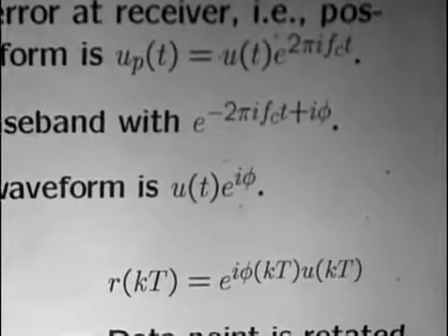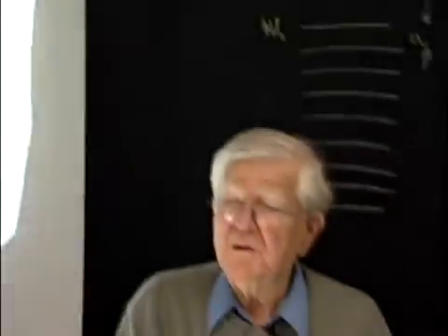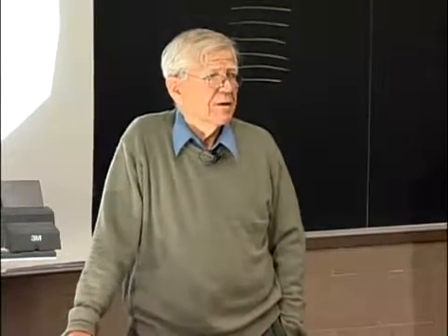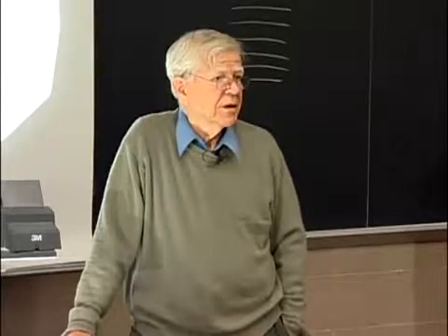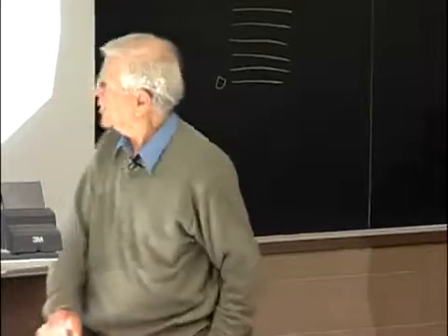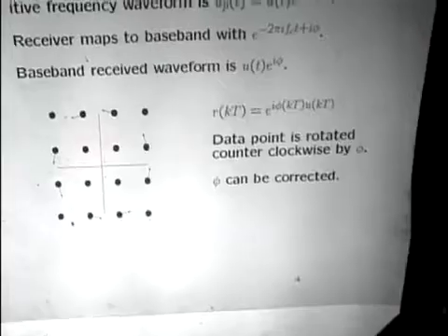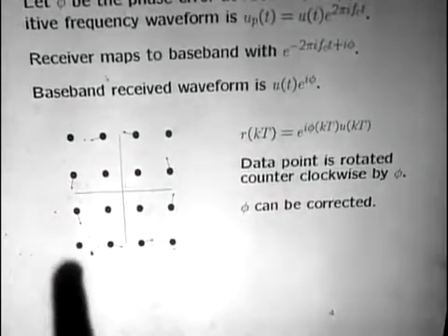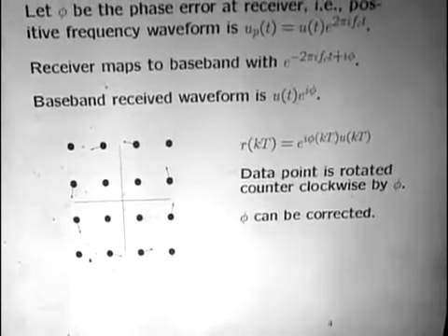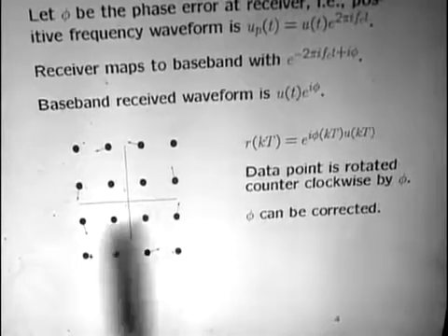Now suppose you're sending analog data. What happens here? Well, with analog data, you're absolutely up a creek without an oar. Okay, there's nothing you can do. But with digital data, there is something you can do. And I think this diagram makes it clear if you can see the little arrows on it. What you're transmitting is QAM signals out of a QAM constellation. So you're either transmitting this or this or this or this, and so forth.